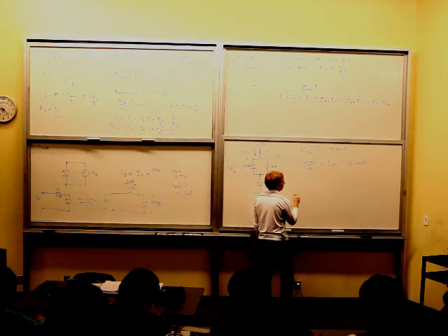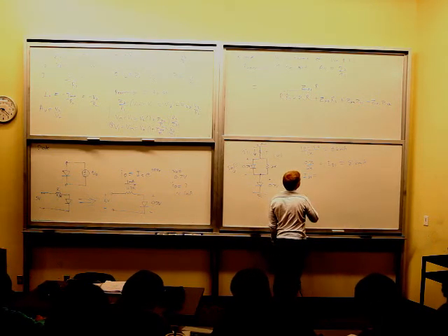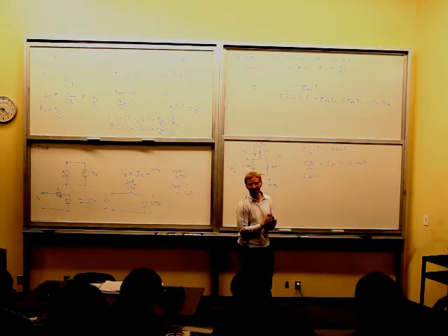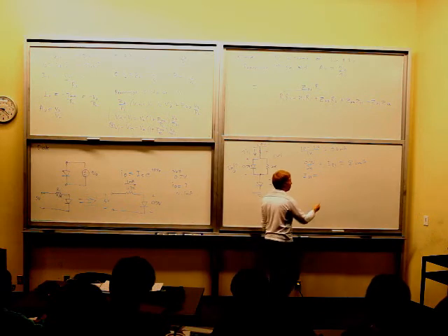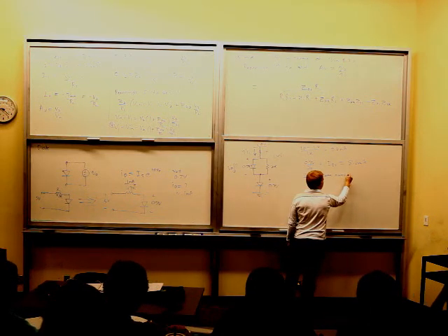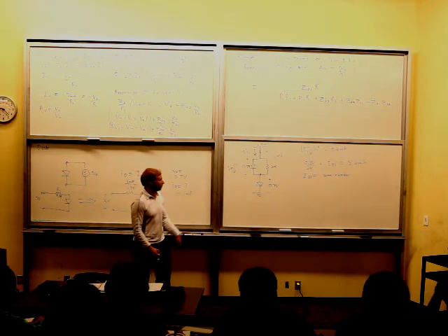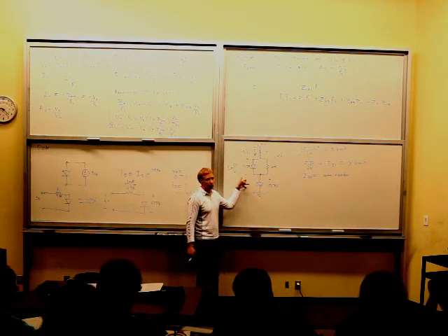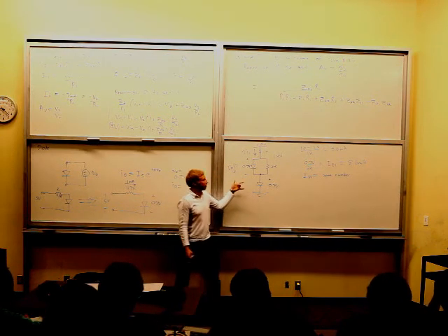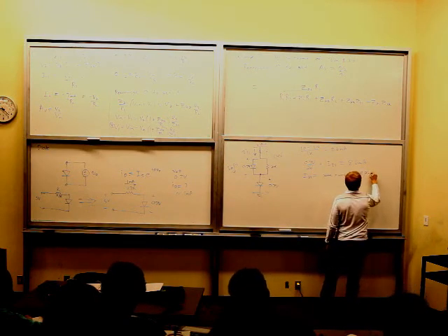And then somebody with a calculator could solve ID1 in milliamps. Anyway, doesn't matter. It equals some number. So watch what I did there. I just assumed that there's a 0.7 volt drop across that diode. 8.25 milliamps. Okay.